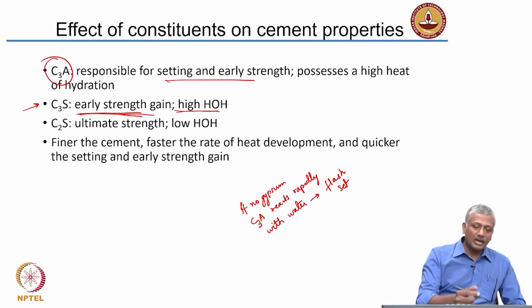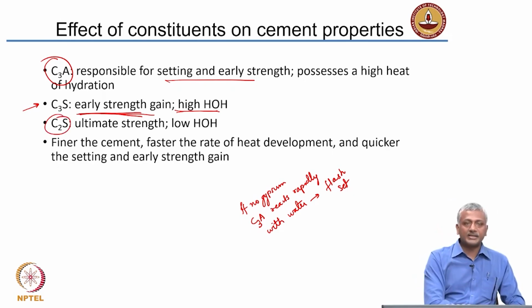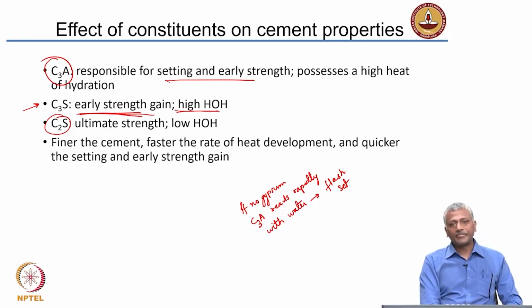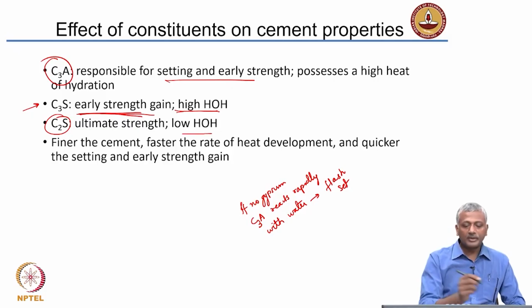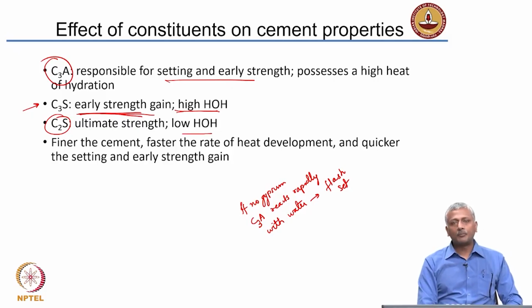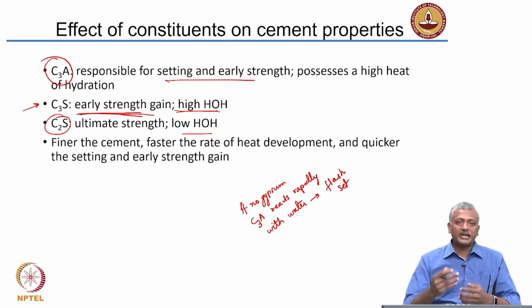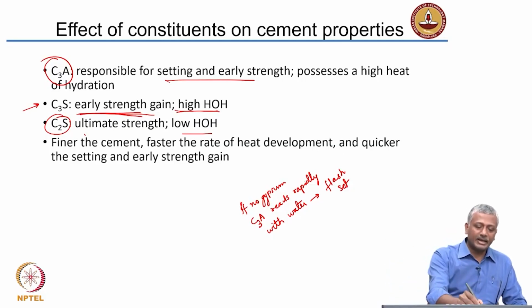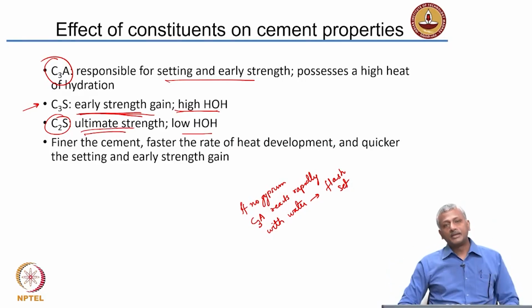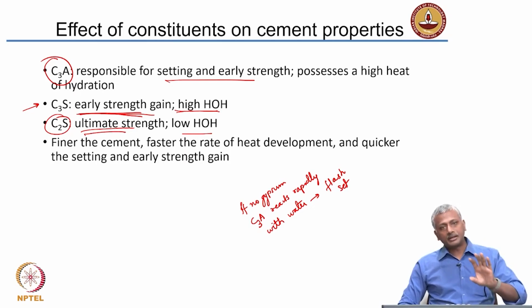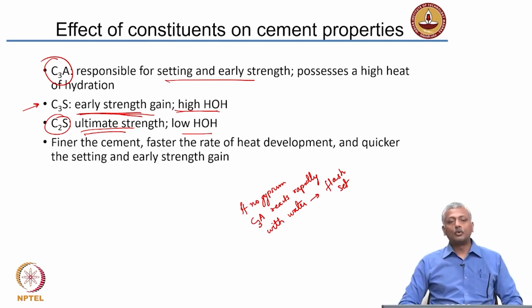On the other hand, when you have a cement which is rich in C2S, dicalcium silicate, it is very slowly reacting and it has a low heat of hydration. So, it will possibly not even react in the first few days of cement coming in contact with water. So, your C2S reaction may actually start very late and it is actually responsible for the long term strength of your concrete. Okay? So, it will slowly be reacting. As long as there is water available, it will continue to react and then provide strength over the long term.